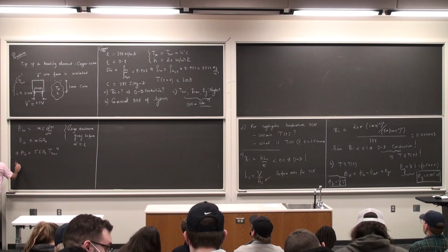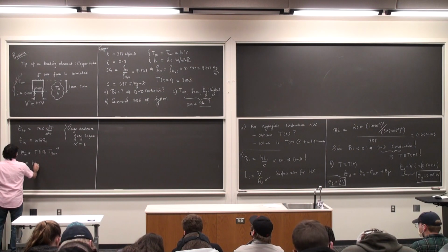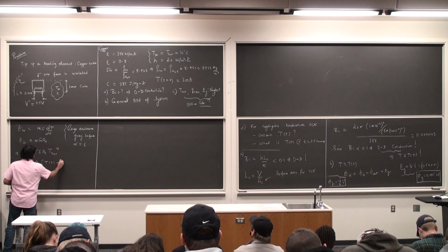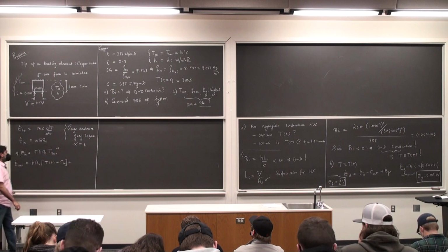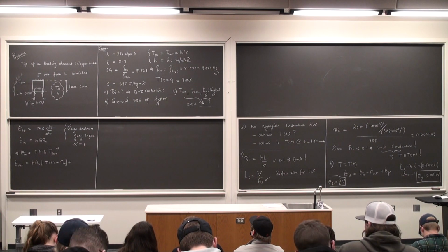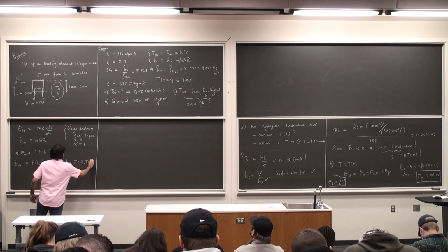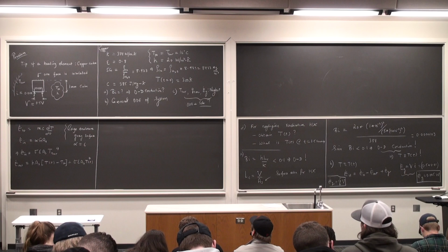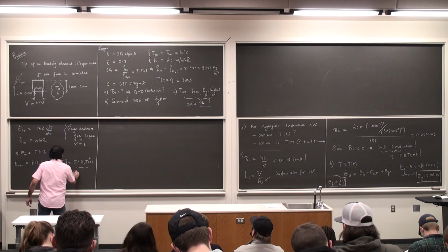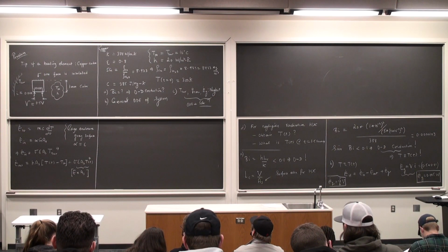E dot out is going to be convective heat transfer, so Newton's law of cooling, h A_s (T minus T infinity). Then there's going to be a certain amount of emitted radiation, which we are going to touch upon today and then for the rest of our semester before going into convection. And so sigma epsilon A_s T to the power 4. Capital G is irradiation. This is the emitted flux multiplied by the surface area. E is the emissive flux.